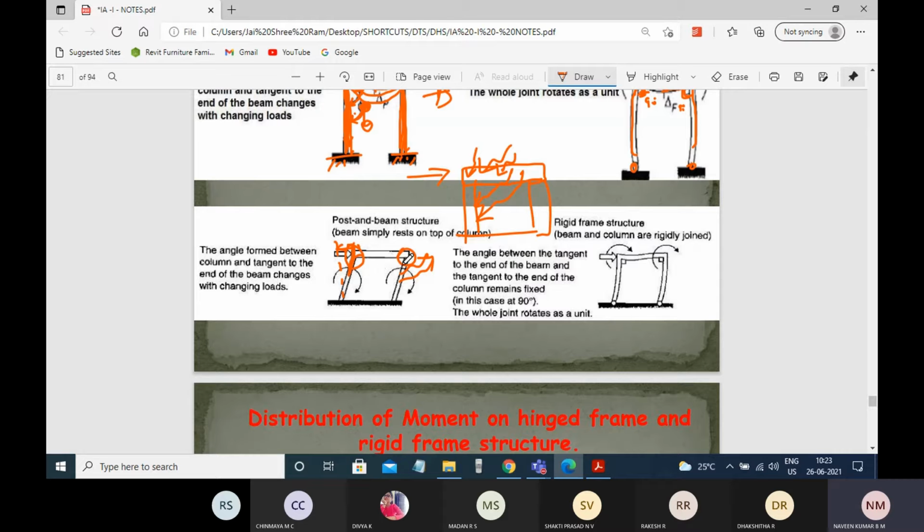You can expect a joint between beam and column. So this is not monolithically cast: the columns are separately cast and beams are placed on them. Then if I apply the lateral load, you can see the displacement, the overturning of the base, and the rotations. If I cast monolithically and apply the lateral load, then you can see the behavior of this particular structure.